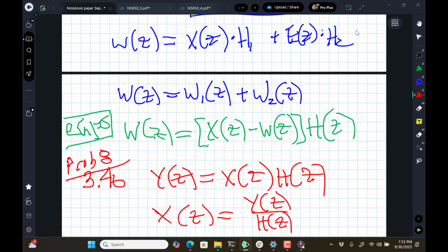We're starting off with a two-sided sequence, and then what is x of z going to be? Just have to think about it. Unless you have a pole zero cancellation, the annular region will stay there, but you might have a pole zero cancellation.